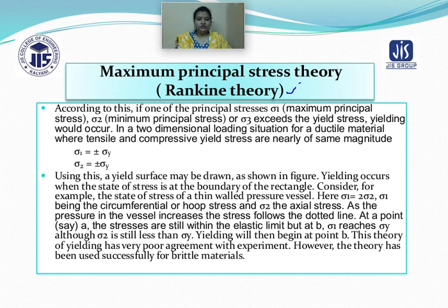The theory of maximum principal stress failure is successful for brittle material, because in ductile material this cannot occur. You can see the stress increasing to some extent, then the upper yield point, lower yield point, then the ultimate stress, then neck formation occurs, then you get the breaking point.